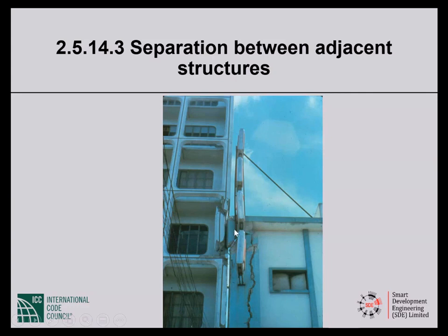I don't know if you see, the shorter building, the taller building, it is not very visible, but this is a dangerous situation. If the floor hammers against, let us say, the mid height of the column, sooner or later the column is liable to give. If, however, the floors were aligned, this floor were here, then the heavy floor would hit against the heavy floor, which is not the best situation, but that is unlikely to cause unacceptable damage. That is unlikely to cause something like collapse.